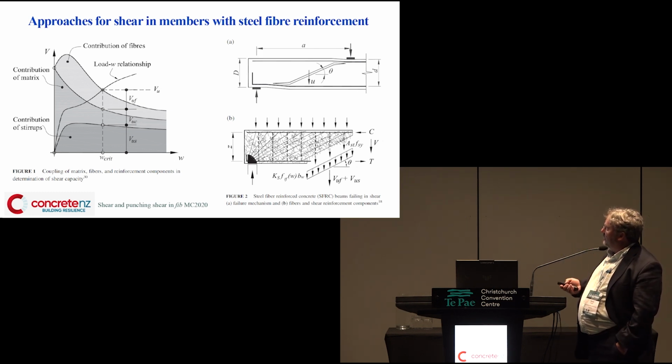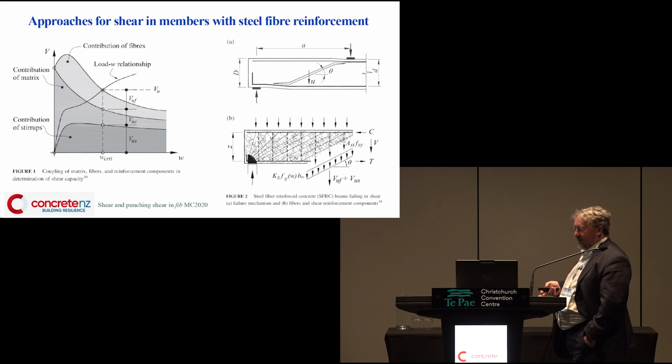Of course, everything is tied to crack width. So the reinforcing steel is also tied to crack widths, the concrete component and the steel component. And the reason this steel is tied to crack width is because as you get the crack widths going up, you actually get a slight decrease in the steel component, right? The steel's yielded as plastic, that hasn't changed.